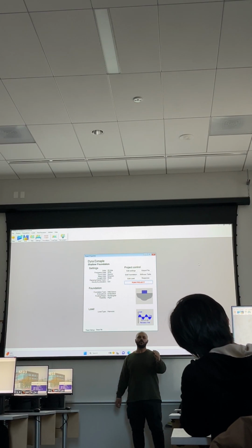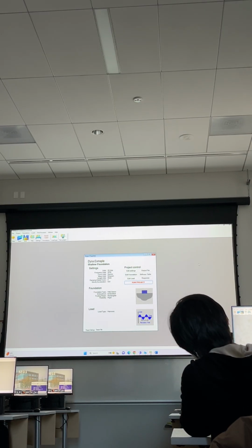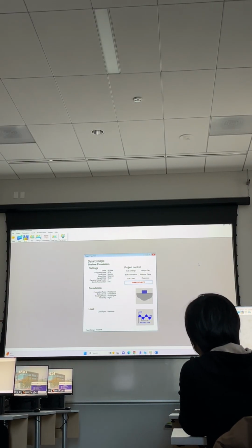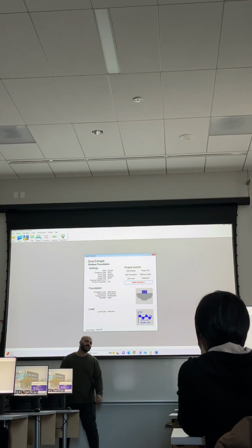If there is no eccentricity at all, that means that we don't have any dynamic force. So we need the rotating part to have an eccentricity, very small, like 0.1, 0.2, something like that. Okay, so this is the eccentricity. And what is the omega? This is the operating frequency.